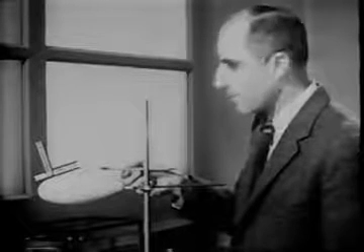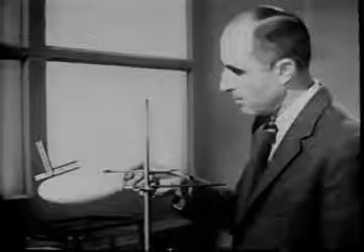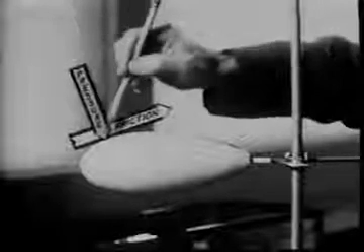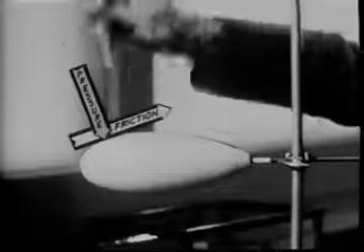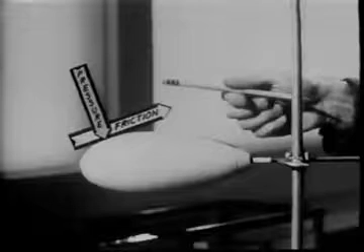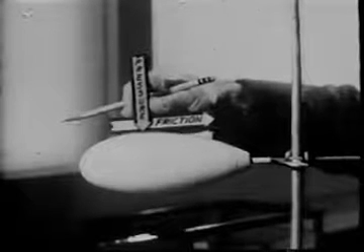At the shoulder, the pressure force has zero drag component, while here near the tail, the pressure force has negative drag components. That is, the horizontal component of the pressure force actually thrusts the object against the flow.